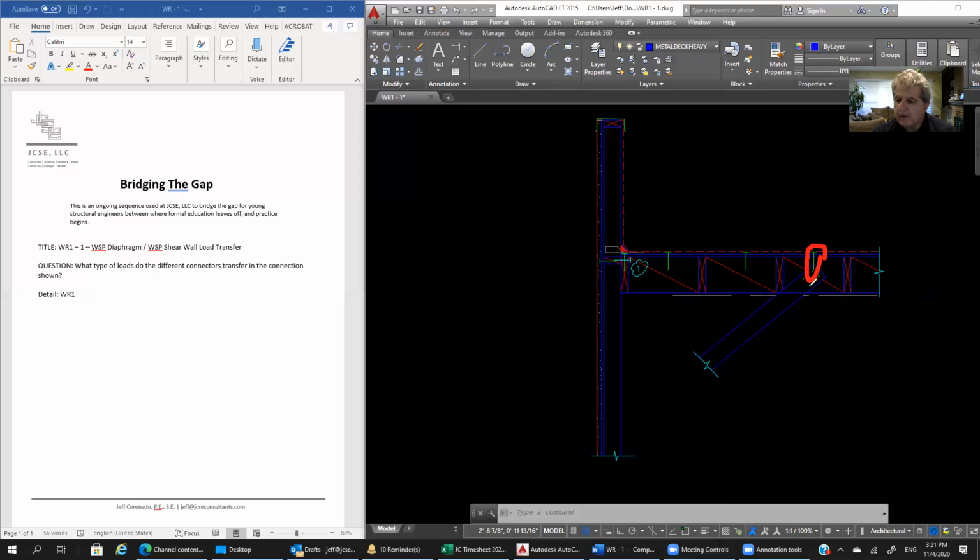As it stands right now, we would be able to transfer the force from the brace into the diaphragm through this length of diaphragm. The length of that block isn't a whole lot, right? That length of diaphragm may not be adequate to resist the entire horizontal force that the brace brings. The brace will bring in a certain amount of force, and this amount of diaphragm will only be able to resist a certain amount of horizontal force. That could very well be what is going on with these elements here.